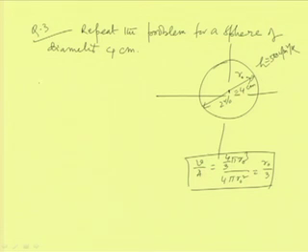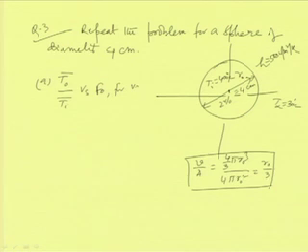Otherwise, for part A, we have to find the dimensionless center line temperature, T naught bar versus T I bar. T infinity is 30 degree centigrade, and T I is 400 degree centigrade. We have the plot of T O bar by T I bar versus Fourier number for various 1 by Biot number.